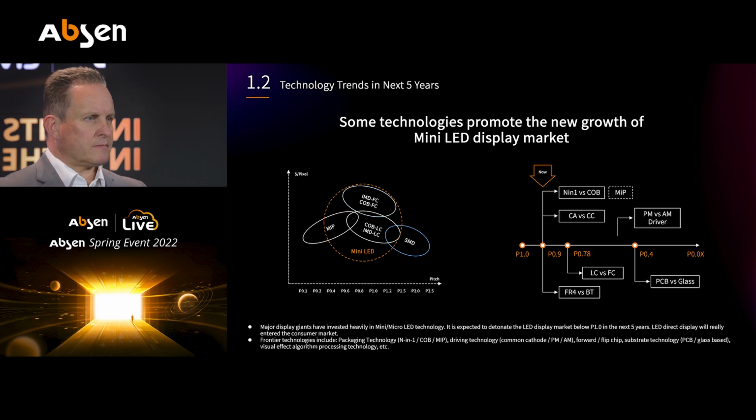We speak about the flip chip coming up and having the lateral chip. This is the mature, already existing SMD and wire bonding technology getting kind of improved. Then we do have the PCB versus glass, which will come up, and all of this, as you can see in the graph as well, guides us to smaller and smaller pixel pitch.